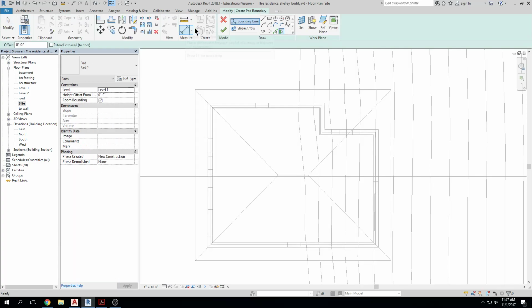Yep, building pad. Okay, so click, click, and this will filter out all of that earth inside of my project here, right? I want this building pad to be defined at basement level so that none of the earth comes in. One thing we didn't talk about yesterday was that you can format your building pad to be a certain thickness, and it makes sense that it's the same thickness as your lower level slab, so that it sits right in line with your slab.